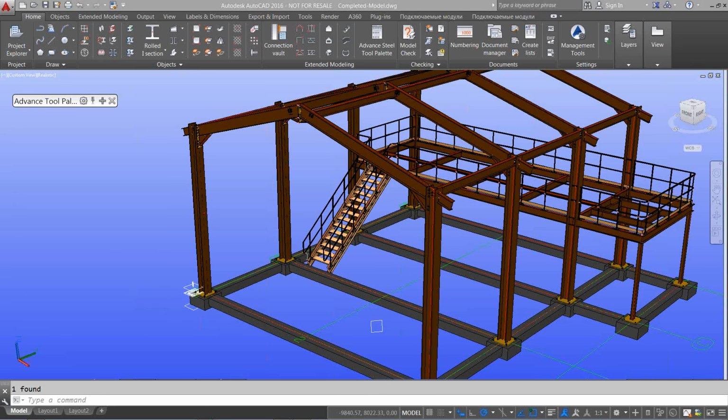One, because I've got one button click to do all the drawings. But for some reason, if you want to take the Advanced Steel model into Inventor, yes, all we need to do is dump these down into normal AutoCAD solids, and then you can take them into Inventor. But in that case, they would be treated as normal dumb solids. They will not be treated as structural members.